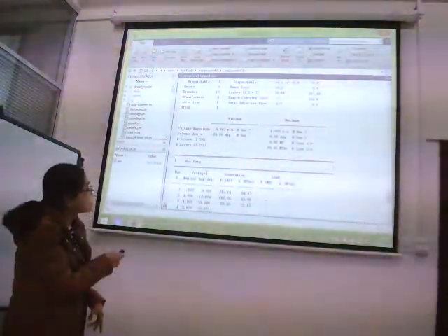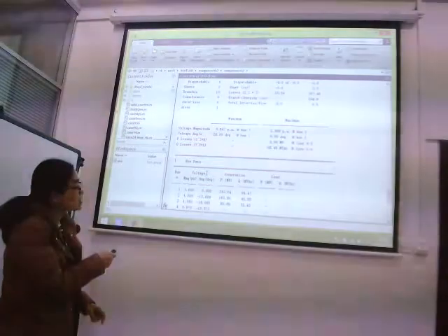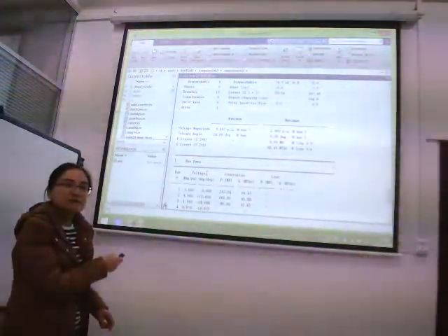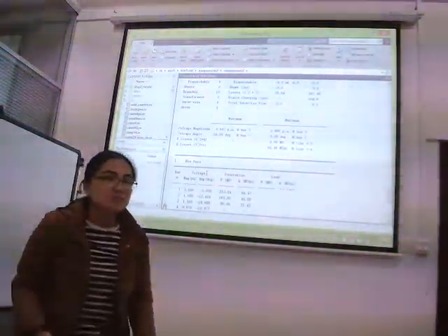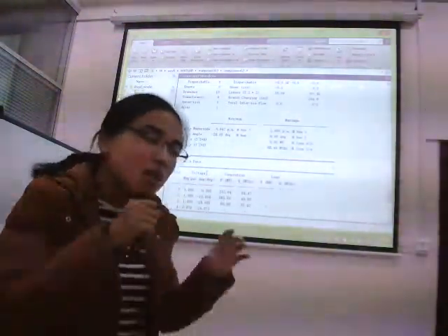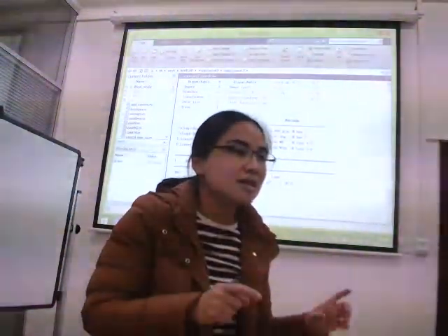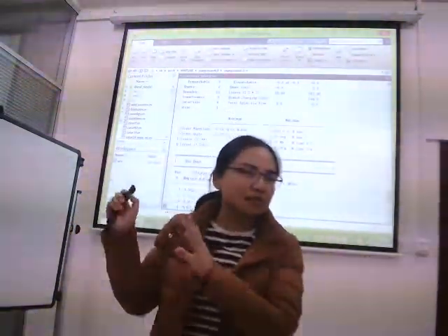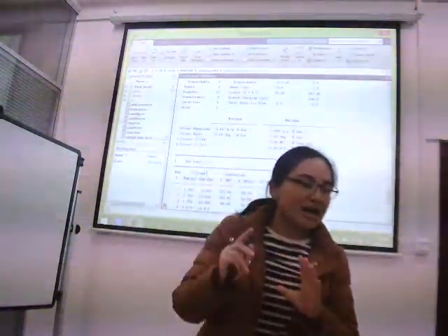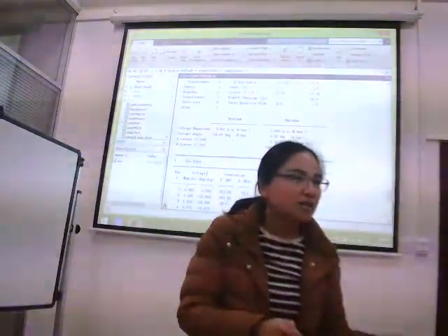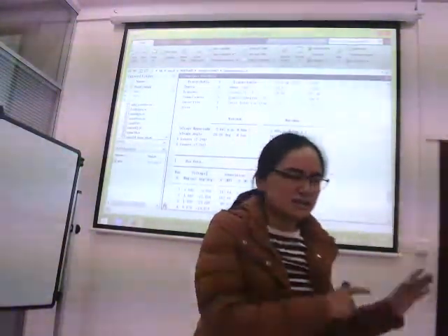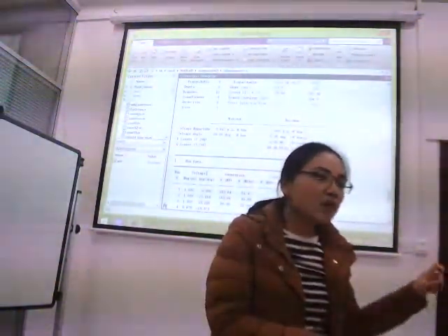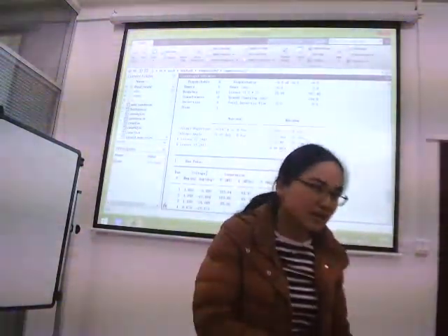Okay? This is the reason why this one is the lowest. Because the load demand at bus 7 is the largest, all the power flow has to flow from other directions to bus 7. The load demand is very large, so the voltage profile here is low.